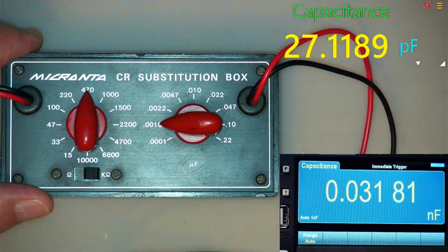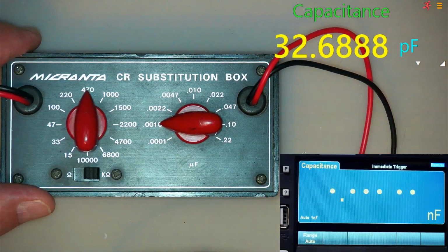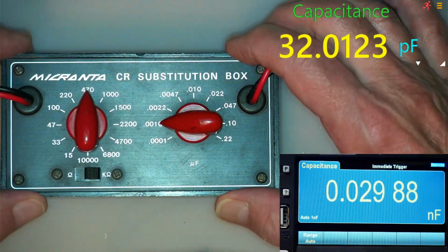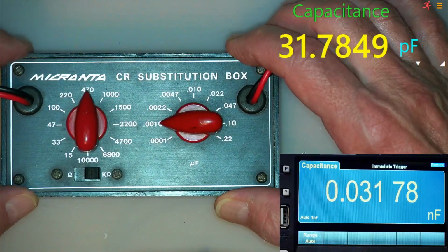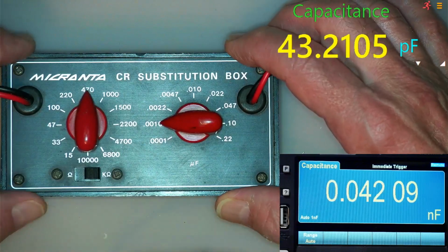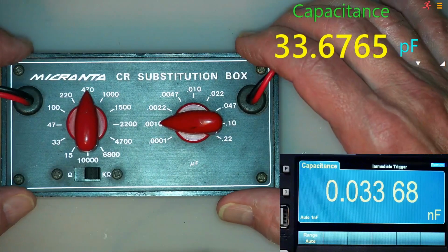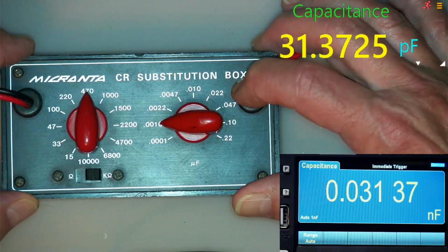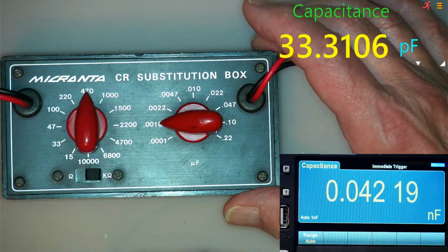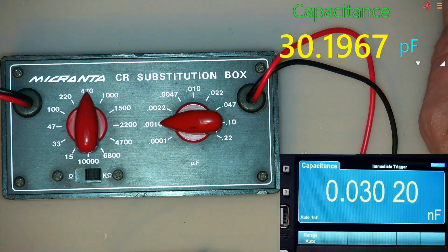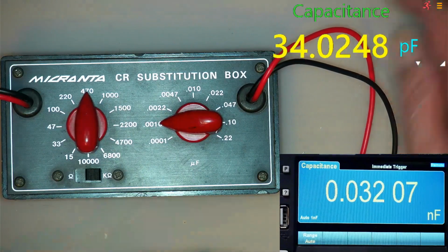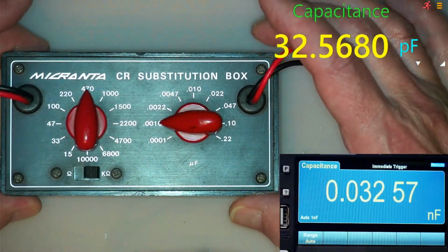So measuring capacitance is not something that you would really do in an environment like that. And besides, I have LCR meters, several of them, which is what I always use to measure capacitance. I don't use my multimeters for that because they tend to be less accurate, and also they're very slow. Some of my multimeters can actually measure right up to a millifarad, but it can take them quite a while to measure a large capacitor, whereas the LCR meter is almost immediate.